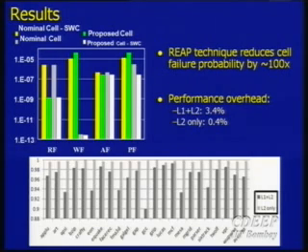But what about the performance overhead if I apply it to both L1 and L2 cache? L1 is in the critical path in your processor, for example. So if you put it in the L1 cache, your performance penalty turns out to be a little bit higher, of the order of about 3 to 4%. But if you apply it only to L2 cache, the performance penalty is only about 0.4%. What does it really mean? L2, my friends in the architecture community tell me, takes about 13 to 14 cycles to write into. So if I add one more, it probably doesn't matter.